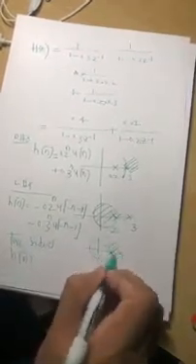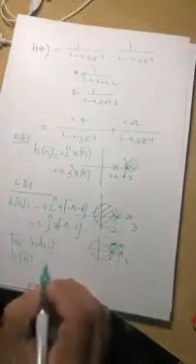right hand side and left hand side, a two-sided sequence. The two-sided sequence is inside a ring like this, between 0.2 and 0.3. Okay, so h of n is 0.2 to the n u of n minus 0.3 to the n u of minus n minus 1. That's all.